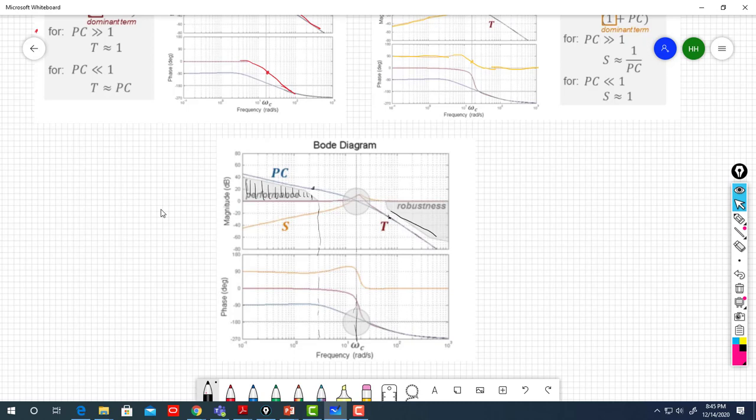So eliminate the... in this case we are eliminating the steady state error and also rejecting the disturbance. Remember, integral effect, pure integral, rejects completely the disturbance. So let's explain why. Because at low frequency, remember 1 over s, it has infinity. So that means a very high gain, so good tracking, good performance in general. Reference tracking, good, so zero steady state error, and eliminate the disturbance, reject the disturbance.